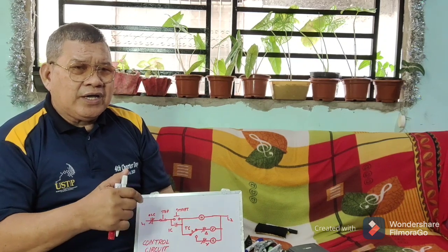Particularly if you are on a ship, you are traveling, and then you don't have a spare contactor. So as a technician, you should have this kind of knowledge. So this is now an initiative. When I looked at the book, I was not able to see this connection. What is being introduced there is always the Y delta using three contactors.